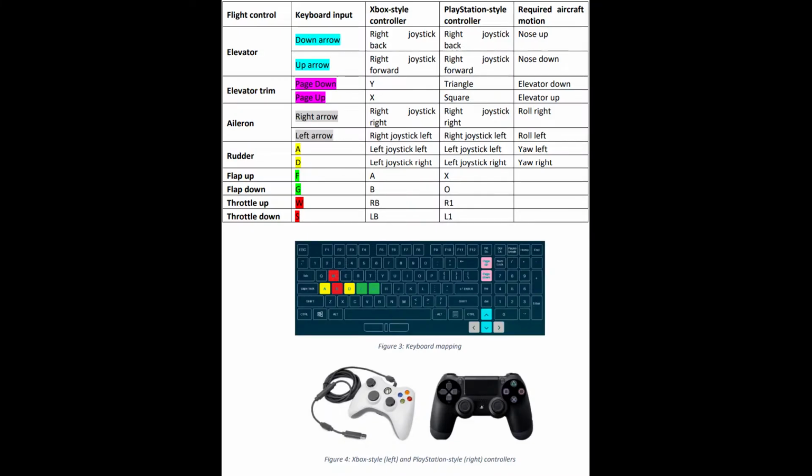The aircraft can be controlled using the controllers and associated bindings showcased in the figure. To achieve control effect set, the polarity must be turned on for the aileron, rudder, and elevator in the Unity file.